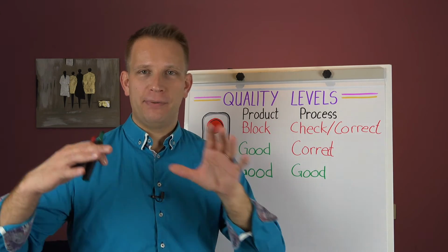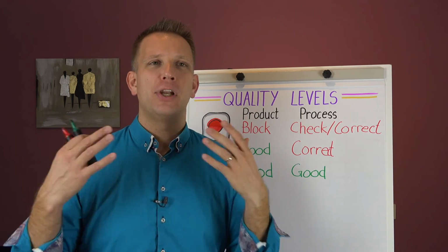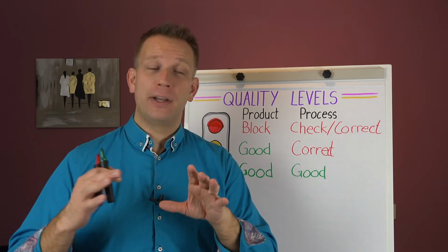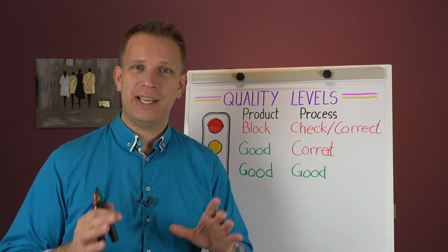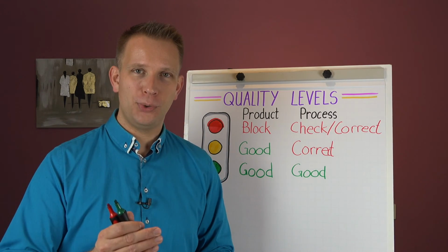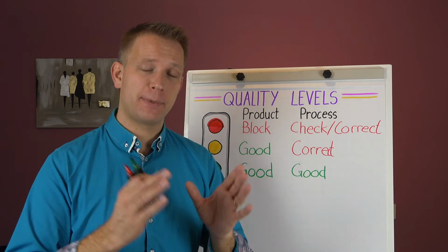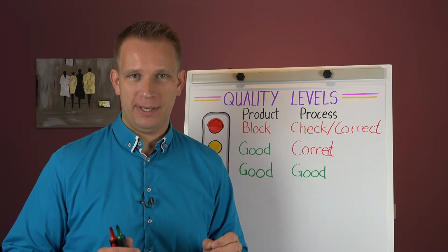Now, if you followed a bit of SPC and specifications, then you know that the two, they don't have a lot to do with each other. Now, there is some link in how you set it up, but there are no product specifications in process control. There is what do you expect the process to do? How can you check if the process is still behaving in the same consistent way? And those make process control limits.